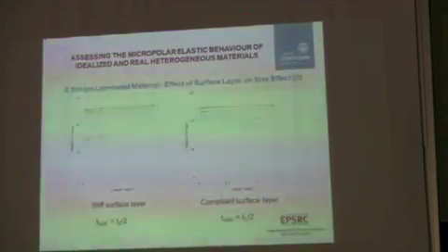And you can compute the stiffness in this case very easily, because you can analytically calculate the flexural rigidity of a simple laminate like this. But if you have the surface layers compliant, you see an equal and opposite size effect.